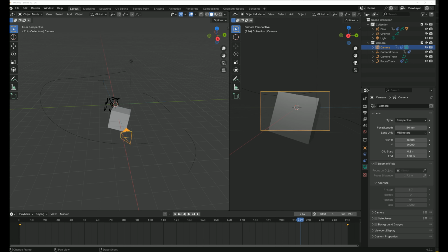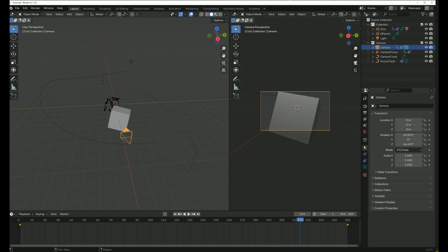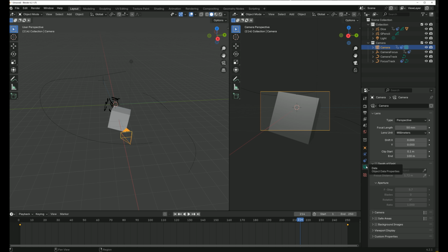All right, to wrap up this video, let's leave off with a couple tips and tricks and something cool that can add some stylization to your videos. To do that, we're going to make sure we're in the object mode. That's important. Click on the camera. We were here on the object properties. We're going to go down to the data properties of the camera, and we have an option under depth of field. I'm going to check that and watch what happens when I mess with the focus distance. I'm going to come all the way down. Boom. See how blurry that is?